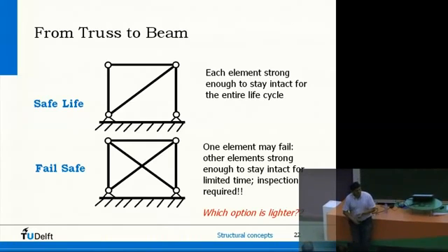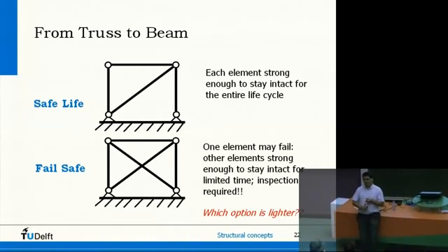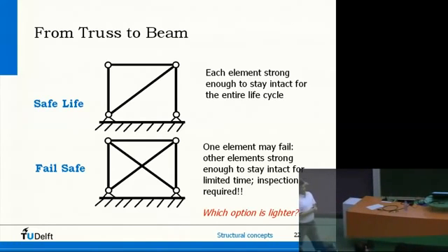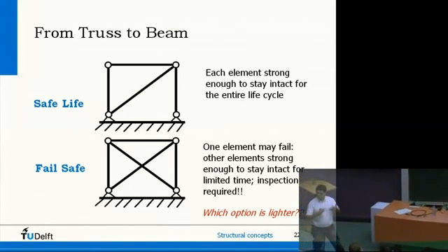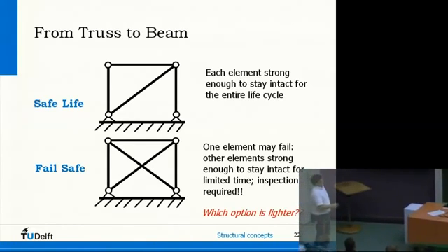And a D check, or the heavy maintenance, is a couple of weeks at the facility. And then the whole aircraft is stripped, inspected from all sides, refurbished again, and can fly around for another 3 to 5 years without such a main check. So,